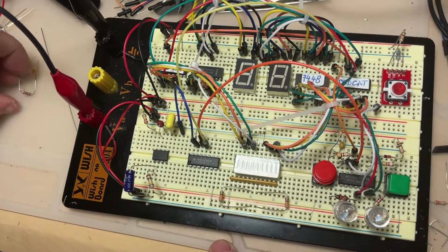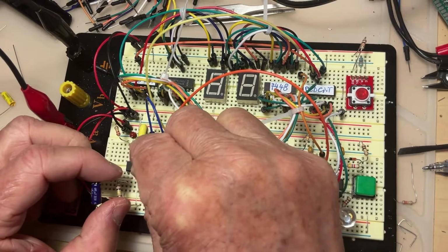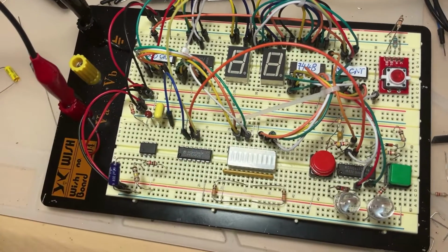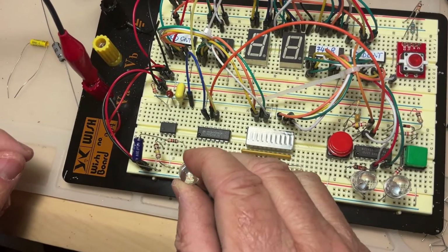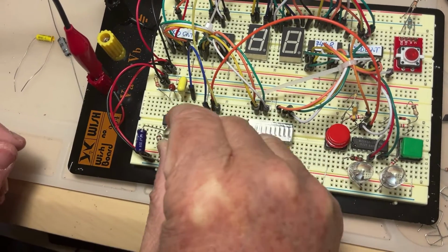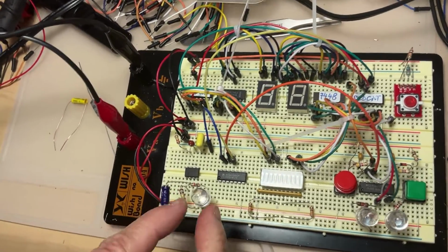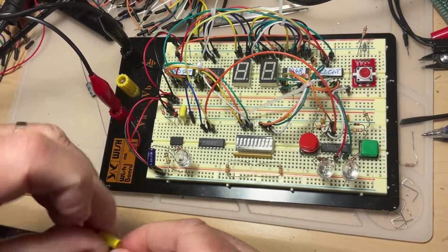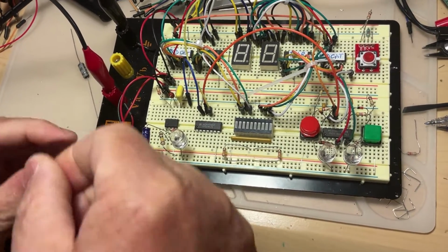Very good. So then from the output, I'm going to connect a 1 kilo ohm resistor and an LED. Don't forget the two things: power off when you make connections, and I'm going to place the two capacitors across the power supply.